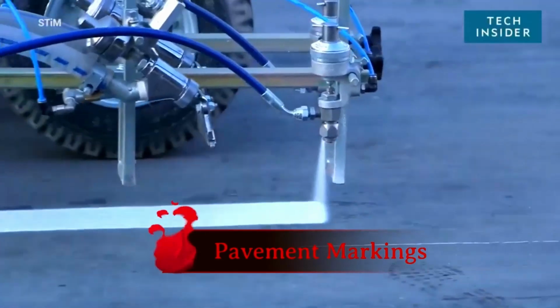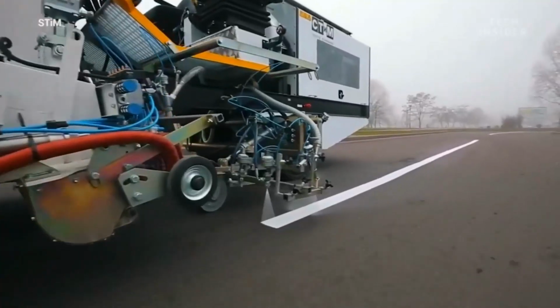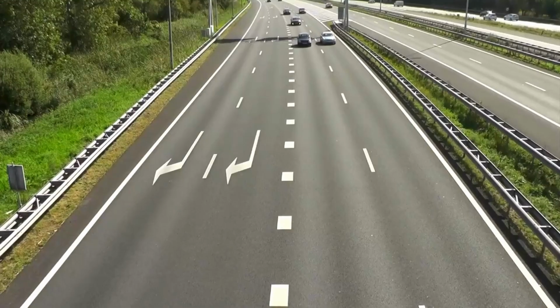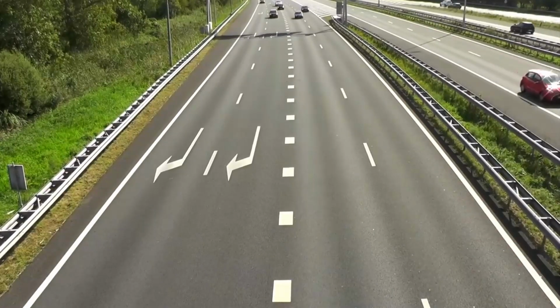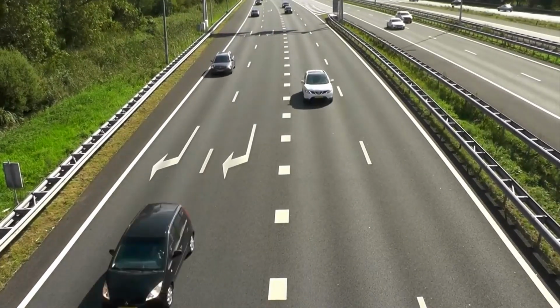Step 7. Pavement markings and traffic reopening. After compaction, the road is allowed to cool and gain strength before opening to traffic. The road is inspected for any surface defects or irregularities. Once the overlay has properly set, the road is reopened for vehicles.